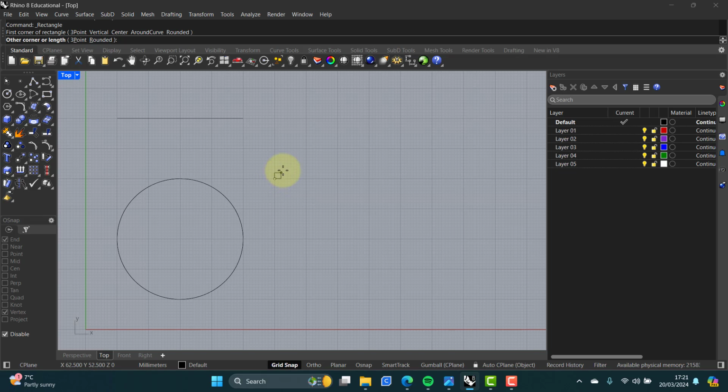So what I want to do is specify the diagonally opposite position. You do shift and at, so it's the A in the circle, and I want to go 20, 20. That means 20 in the X direction, 20 in the Y direction, from where I am just now. Enter, done. Square is exactly 20 by 20.